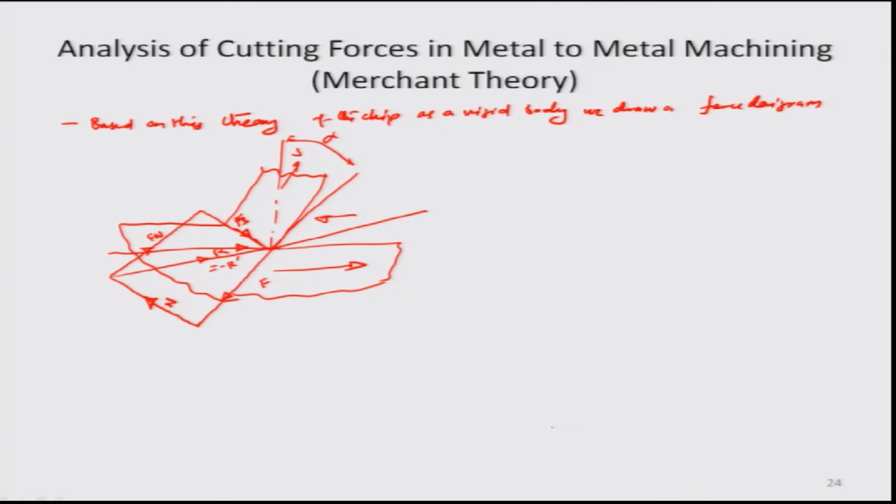And then we have another tangential force that the workpiece would offer because of the cutting process. You already saw that in the case of milling, where each component would offer a force in the perpendicular direction. All these forces together result in a common resultant R, and I can place these forces over the diameter R, meaning that if I draw a circle, it would connect all these forces together, and this becomes the common diameter R over which all these forces are connected.